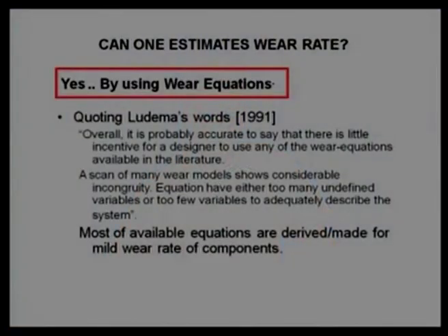Or we can say, if we are rejecting some component, it is because of severe wear, because of the high wear rate. Mild wear we will not be rejecting so fast. If it is severe wear, then we reject, but we will not be able to diagnose what the wear mechanism is. Severe wear may come with a combination of wear mechanisms. So, finding a root cause of failure will always be difficult using one single equation.